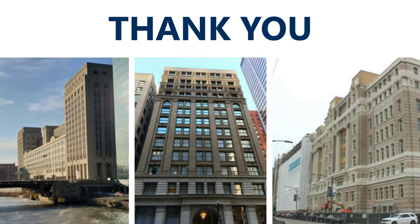Okay, our next question. In general, in regards to work performance, is it best to execute exterior facade repair work from the top of the building to the base of the building, or vice versa? I don't think it necessarily determines whether it's from the top or the base. Ultimately, look at whether there are other conditions you need to address. If there are roofing conditions that need to be addressed at the same time, understand whether there are potential water leakage issues, and think about the building in drops if possible, getting and finishing an entire location.